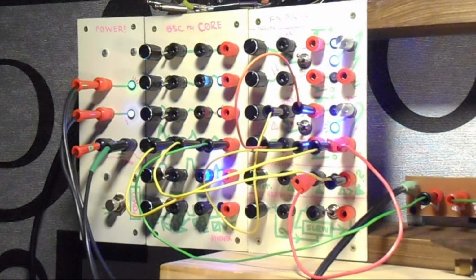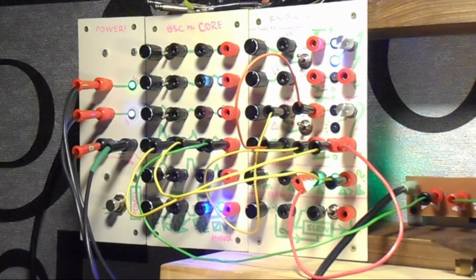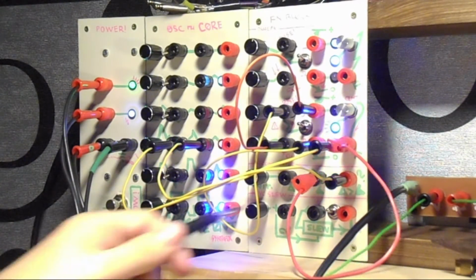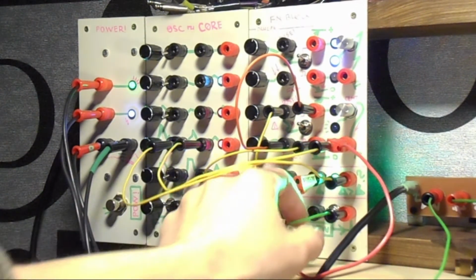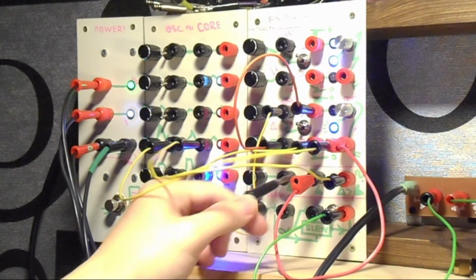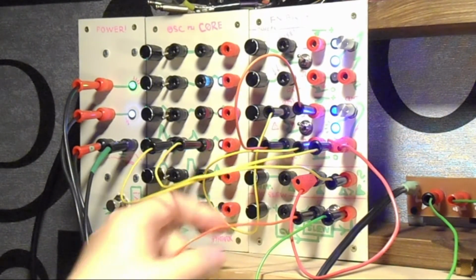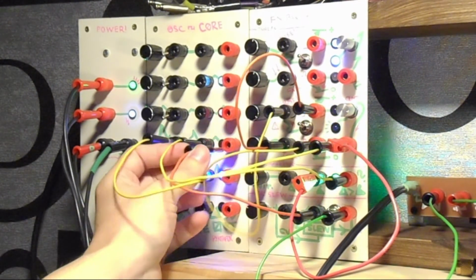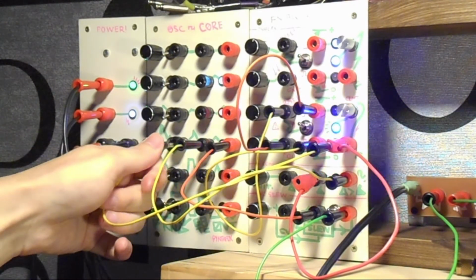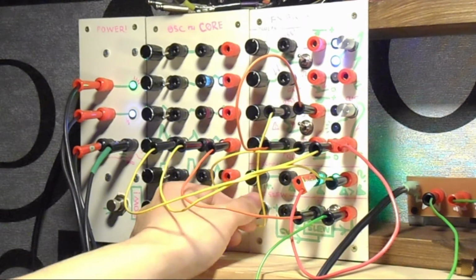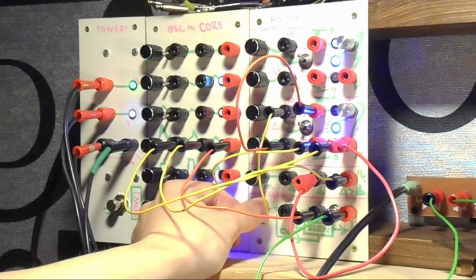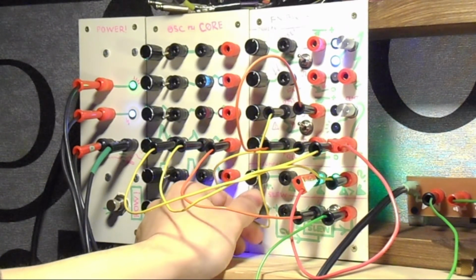Yeah, now it's good. Now we can take our output and not run it directly into the mixer, but put it into the voltage controllable slew, which is right now in the audible mode with the small capacitors, like 5 nanofarads. And as the input of the voltage controllable slew, we provide our oscillator. And now the slew thing can do the filtering effect.